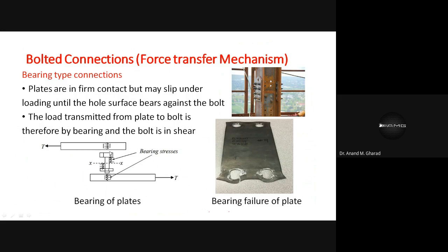So you can see over here the bearing stresses are developed. And why do we expect bearing stresses to be developing? Because you can see when these two plates which are connected with the help of this bolted connection are stressed in this manner, let's say a point will come that this surface of the bolt will get in contact with the plate, and if the grade of the plate is less, then the bolt will exhibit its pressure or force on the plate surface, and the associated failure is the bearing failure.